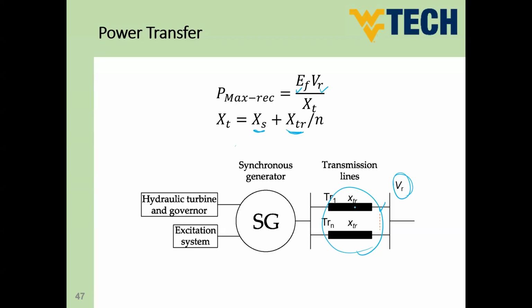So STATCOM, or static compensator, is nothing but a power electronic device connected to a stored energy element, regularly capacitors, and it injects the reactive power to the grid in order to improve the operation of the grid, like adding or changing or controlling the transmission reactance. So this would help a lot in improving the performance of the power transfer on our grids.